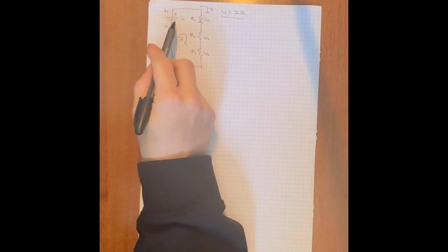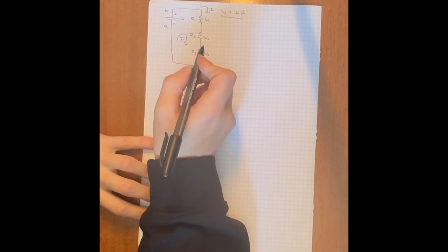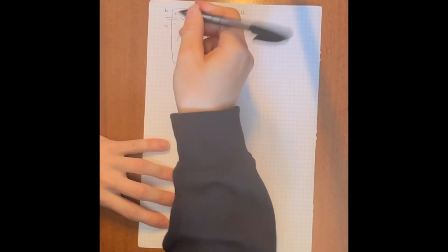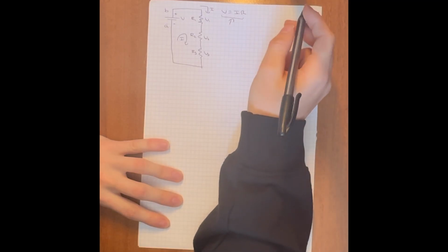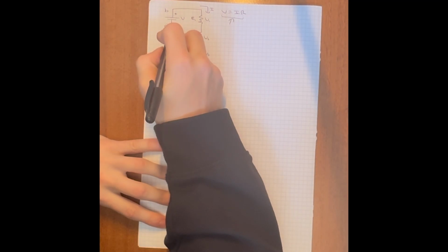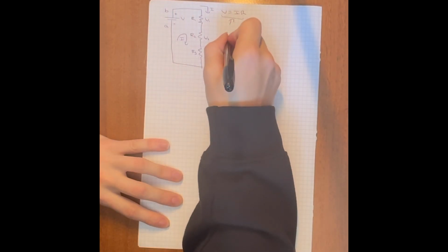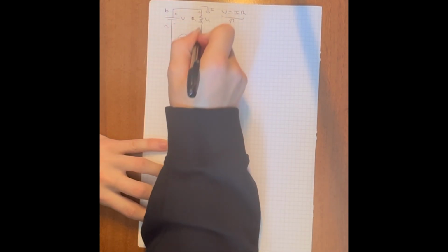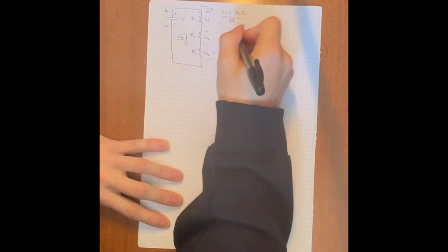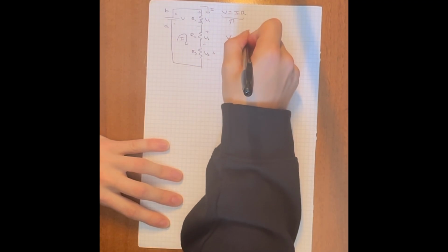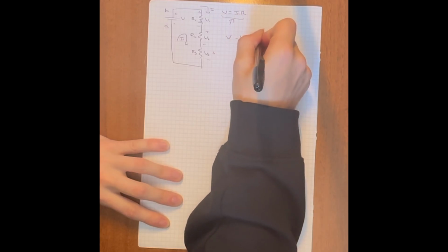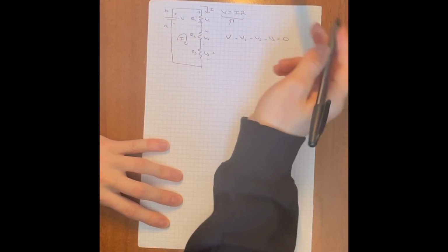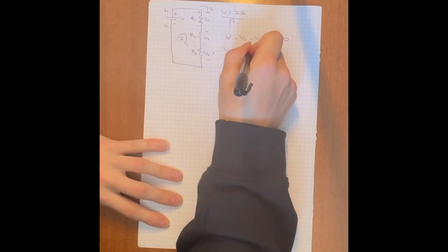So if we're looking at this circuit, for example, and why we get this formula, especially, we can make a simple equation. Here, because it goes from minus to positive, it will be positive, and because when the current flows through this point here, it's going to be positive, negative between each resistor. So that's why we get a voltage drop. We're limiting the voltage. So it will be minus V1 minus V2 minus V3, and that equals 0. So now let's put all of them on the other side like this.